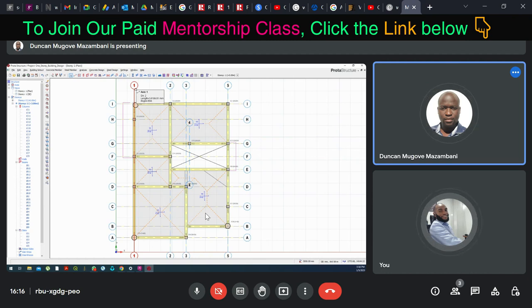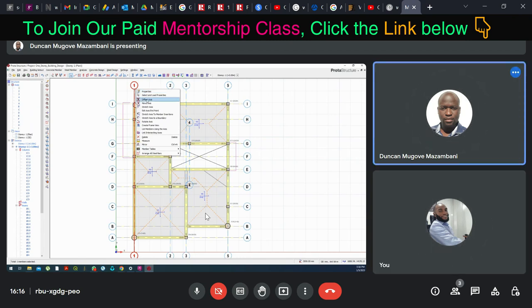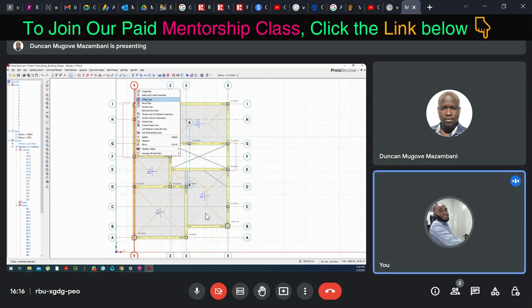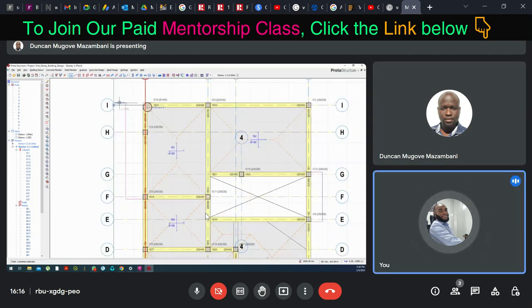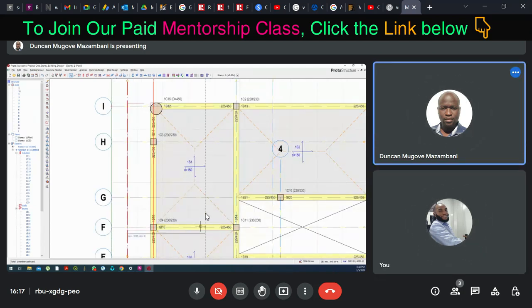Click on that grid line, right click and you see offset. Offset axis. Click on it. Now zoom in and click at the edge of the cantilever. Click there, at the edge.